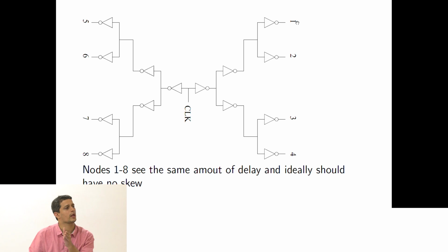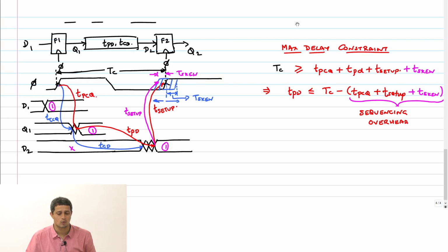With respect to that, what happens to the next node is what we are saying. So what you are saying is, what if F1 arrives late? So, okay, if this arrives T skew later, right?